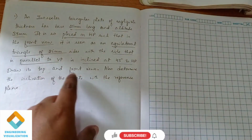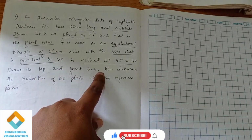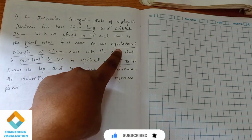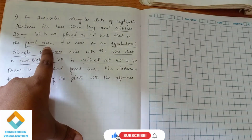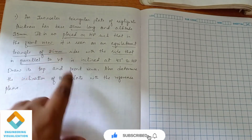Instead of that, they are telling that the side that is parallel to the VP is inclined at 45 degrees to the HP. So the second angle of inclination they have not mentioned. Instead of it, they have mentioned a second view. The second view is an equilateral triangle of dimension 25, and it is a front view. So in the front view, we have to get an equilateral triangle.